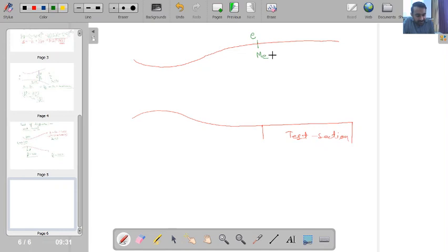So my exit Mach number over here is equal to 3, and I am not concerned with the pressure over here, but I am concerned with the pressure at this point, because when the flow exits into the ambient, it should have atmospheric pressure. So here my P infinity should be equal to 1 atmosphere. After the test section, the duct supplies flow at 1 atmospheric pressure, and just over here I have Mach number of 3, and say the exit pressure is PE.